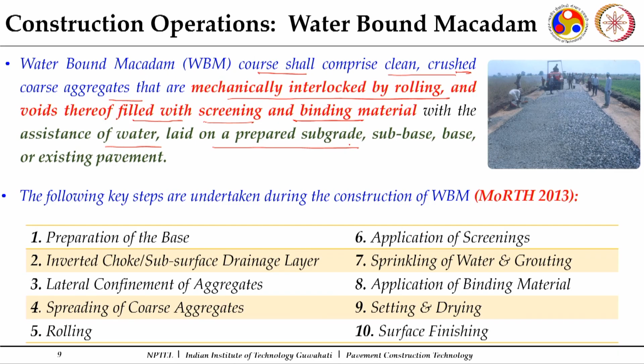If I am using the water-bound macadam as a sub-base course, then it will be laid over a prepared subgrade, or it can be on a sub-base course also, or a base course also. And even sometimes when we are going for strengthening of certain pavements, you may have to construct a base course.